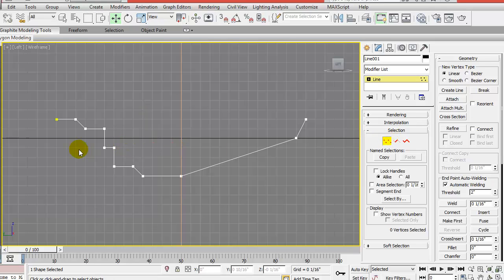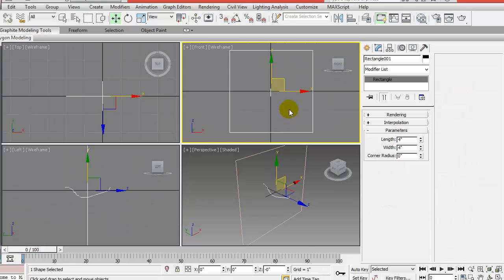Now let's edit these nodes. Select fillet and select this one here. Pull it so that it becomes a curve in both cases. Exit fillet, and also let's weld these vertices so they become one. Alright, so we're done with this.